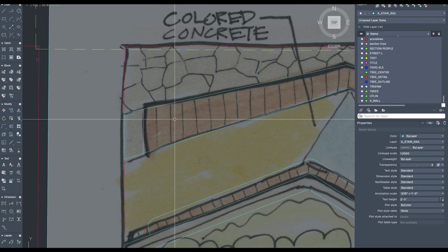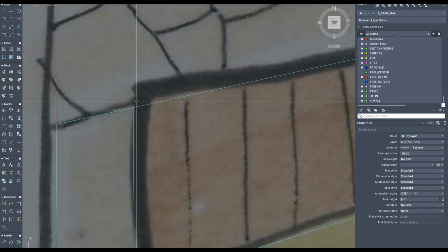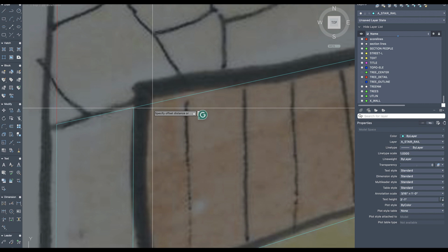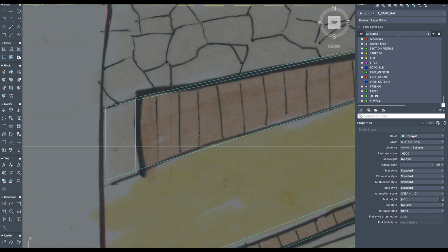I'll have slats that sit on top of the concrete, and it's probably going to overhang just a little bit over this concrete. So what we'll do is decide in our detail what that overlap or overhang is going to be. Just for now, we're going to estimate about a 2-inch overhang. We might have a bull nose or something that makes this a softer edge than just the corner of that. But we'll do a 2-inch overhang on that side. We'll offset 2 inches on this side and extend that line out, and of course trim this